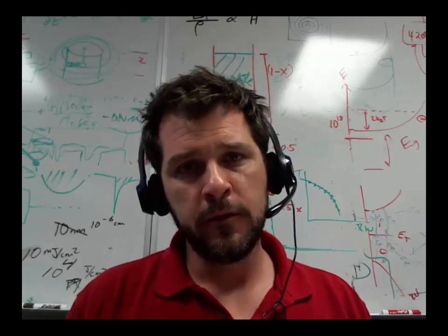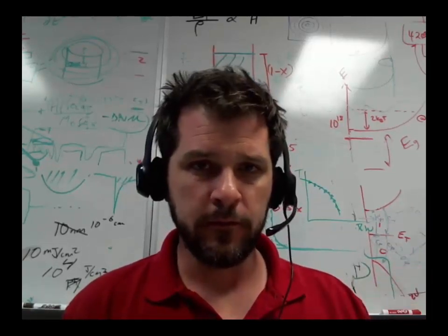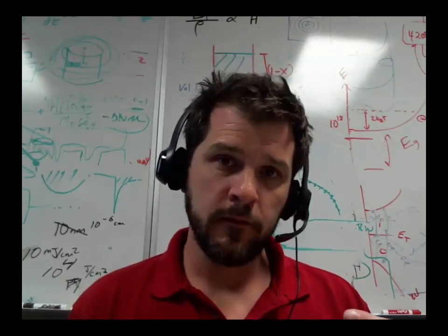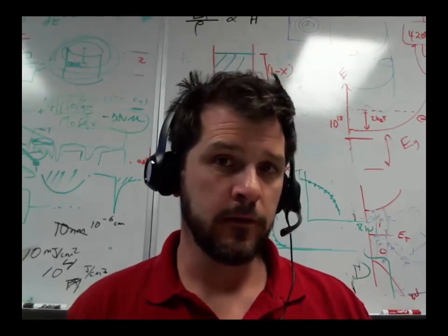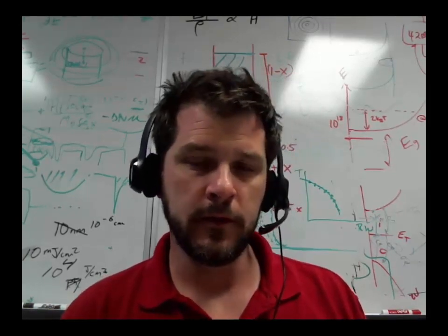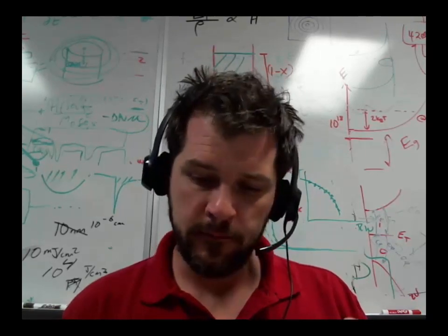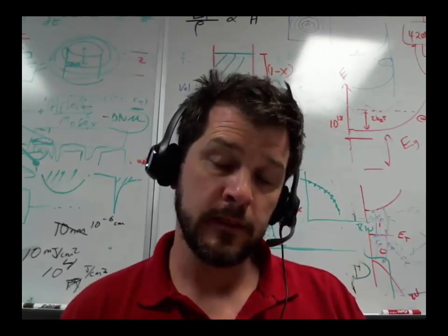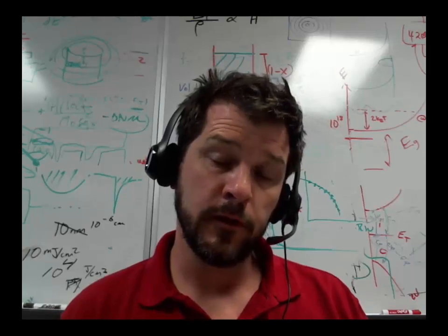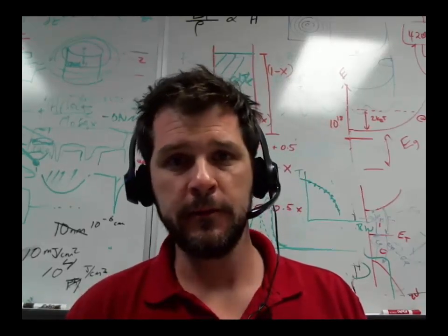Alright, so in these two videos we've gone through and seen the basic current voltage curves of the MOSFET. We've looked at phenomenology and the equations that govern the source drain current as a function of source drain voltage. We've seen how the gate voltage affects things in terms of changing that channel charge and moving you above and below threshold to turn the device on or off.